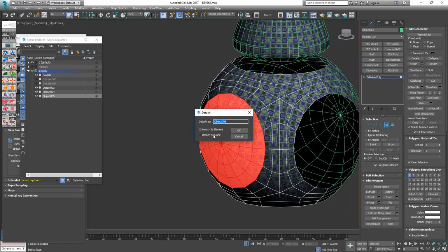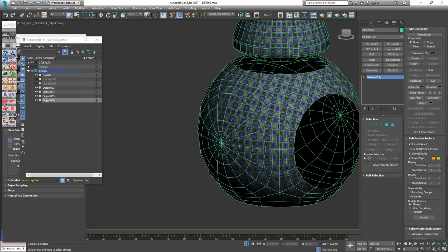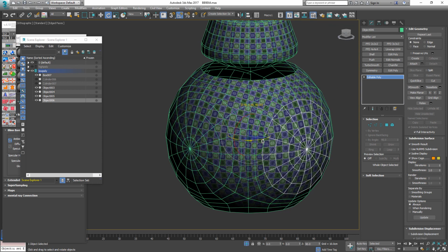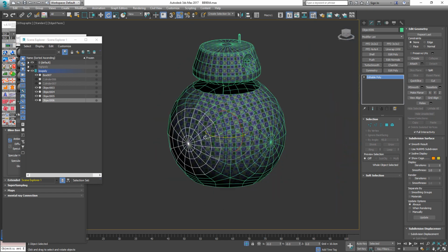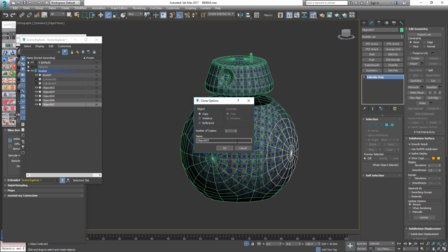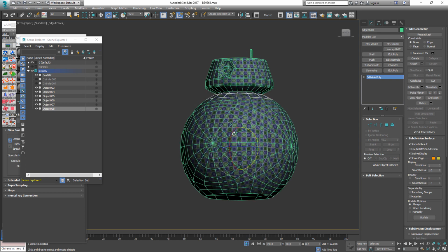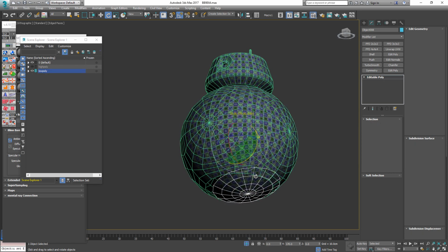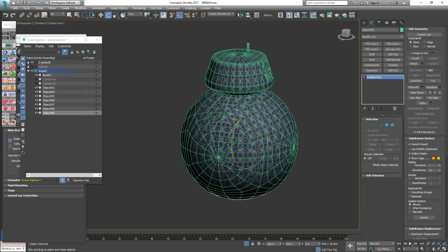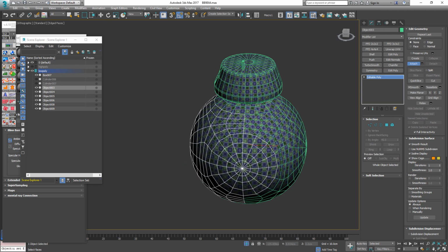So that means all that we have to do is detach it as a clone here, these rings or these caps, select them, and then with our snap on, we're gonna rotate it over here, that copy. And now with Shift, we make another copy over here. And the same goes for the top and the bottom cap here. With Shift pressed and 180 degree rotation. And that means we don't have to go back into the UV editor for these parts because we already did that when we copied the first half over.